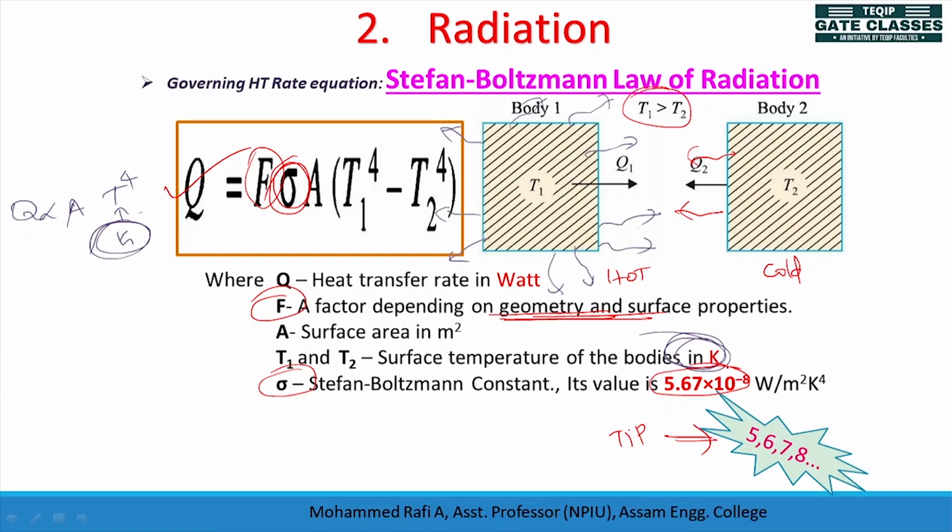Now here it is minus 8. That is why you will not feel any energy loss, because our body temperature is 37 degrees Celsius. If I convert 37 plus 273 and take this to the power 4, the heat transfer will be that into 5.67 into 10 to the power minus 8. This is a very small value, so the quantity of heat transfer will be very small. But at a high temperature, it will be an appreciable value. It will be more than conduction or convection.